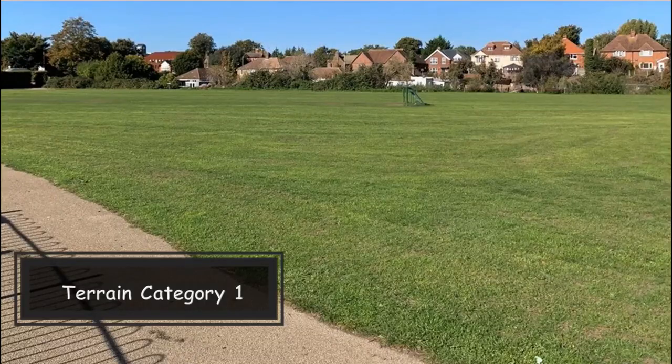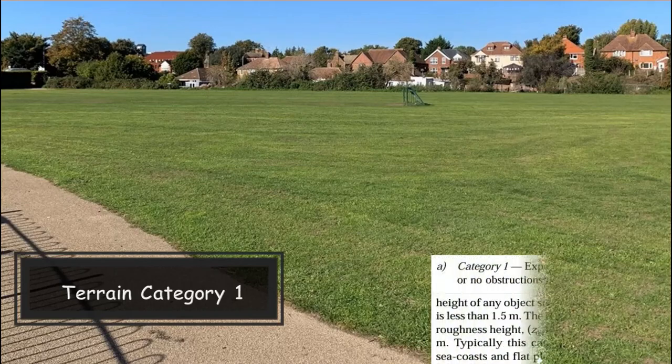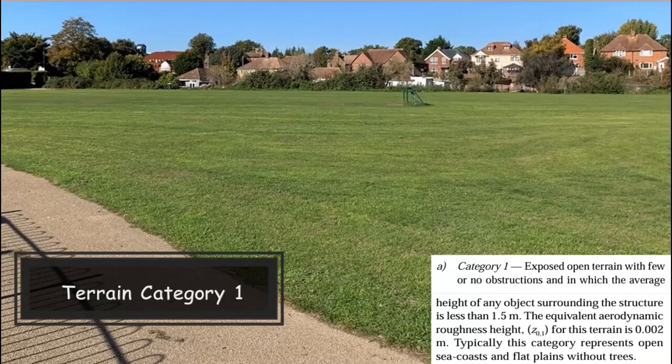The second factor is the K2 factor, that is terrain factor. In IS 875, there are 4 terrain categories. Category 1 is the open terrain with few or no obstruction, in which the average height of any object surrounding the structure is less than 1.5 meter. This category mainly represents the open sea coast and flat plains without trees.